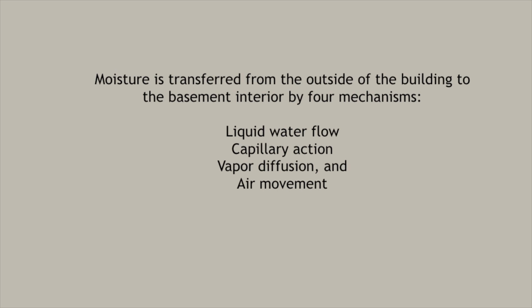As a home inspector, you should know there are 3 sources of moisture. 1. Liquid water from rain, or groundwater, such as underground streams. Rainfall, amounting to 1 inch per hour, is approximately 1,250 gallons of water on the roof of a 2,000 square foot house. Depending on the season, below-grade water table can also rise due to flooding or seasonal conditions, such as